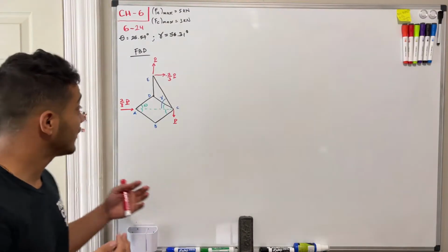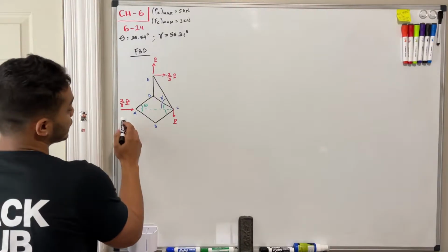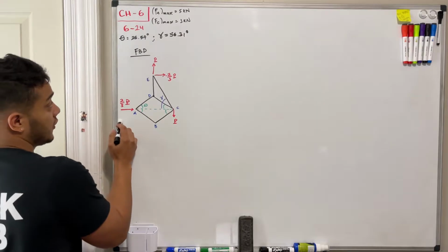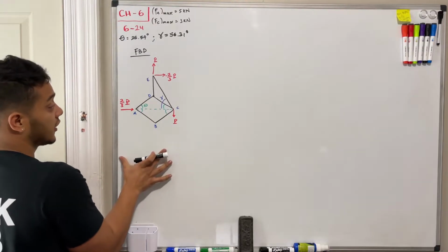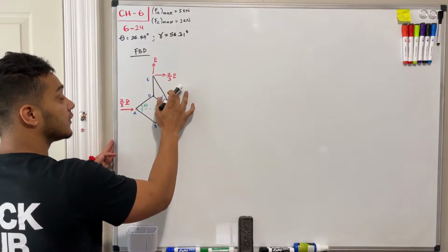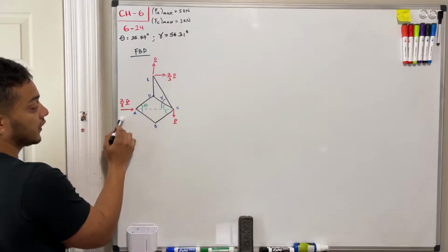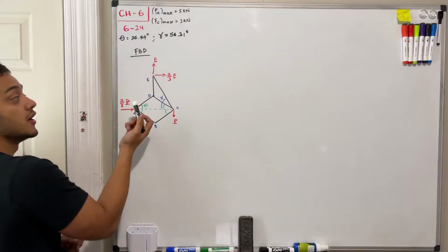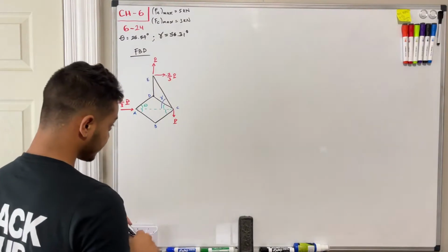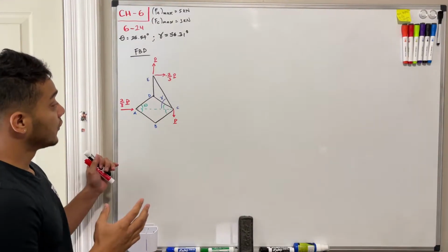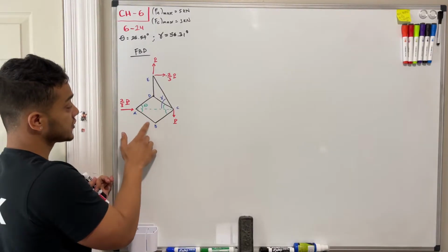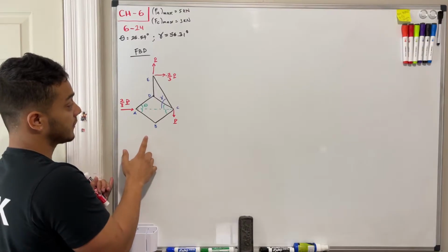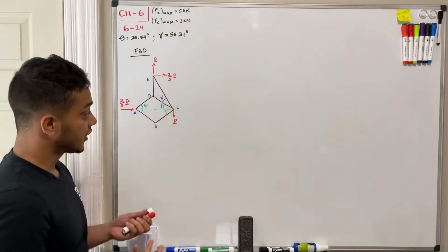Okay, so after solving for our reaction forces at A and our point E, we can draw our new free body diagram with our updated values. So 2 over 3 P over here, negative 2 over 3 P if you draw in this direction, and positive P going up. So now we need to know how much force, with respect to P, each member is applying, and if they are in tension or compression.